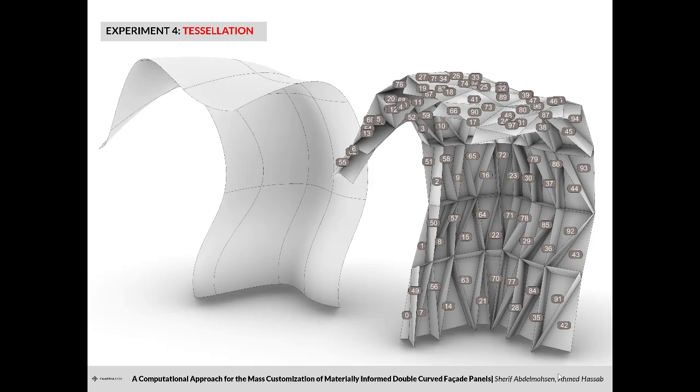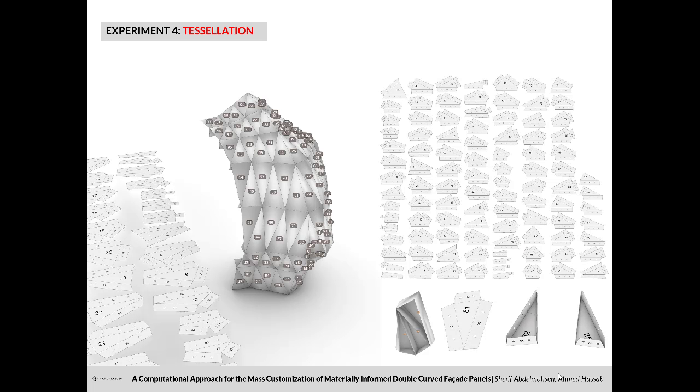The figure here shows an automated surface tessellation and fabrication tagging of the double curved surface using the tessellation Grasshopper script developed. Here on the left is the script output showing surface tags and 2D cutting sheets for panels. On the right are the 2D cutting sheets showing the 3D assembly, panel engraved boundaries, and on the bottom the cuts for connection pins.